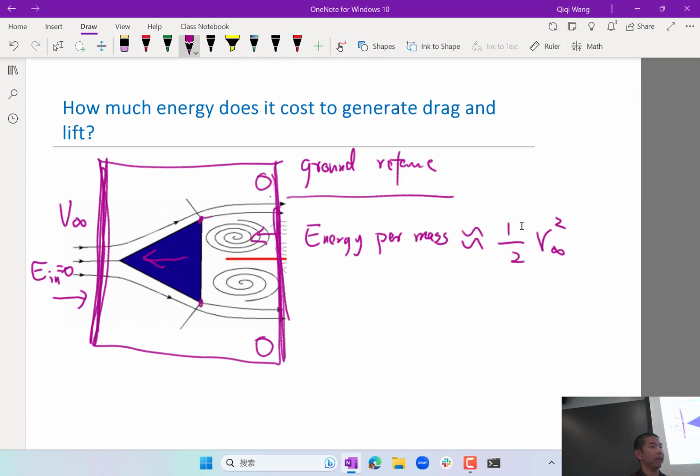Even very streamlined bodies will have a boundary layer, and as the boundary layer goes behind the body, there is going to be a narrow wake, a viscous wake, right? It's going to be much smaller than this, but there is going to be energy that is dumped into the air that is dragged alongside the body to move with roughly the velocity of the body.